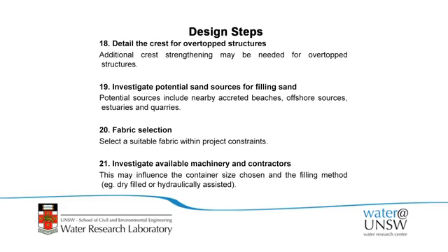If you are going to have an overtopped structure, you've got to design it for overtopping. So you may need some additional crest strengthening of the structure so that the bags aren't dislodged, or if they're dislodged, they don't just fall into a hole and the whole structure collapses. Also, probably at this stage in the project, think about where you're going to get the filling sand from. Nearly always it's from the beach nearby where the structure's being built. If it's an emergency situation with a large amount of storm erosion, that may not always be feasible. So think about sand sources which may have to revert to a nearby estuary or bought in commercial sand from a quarry.